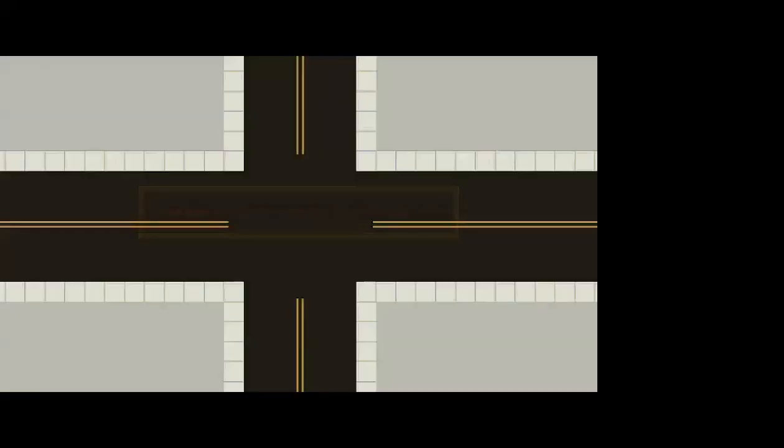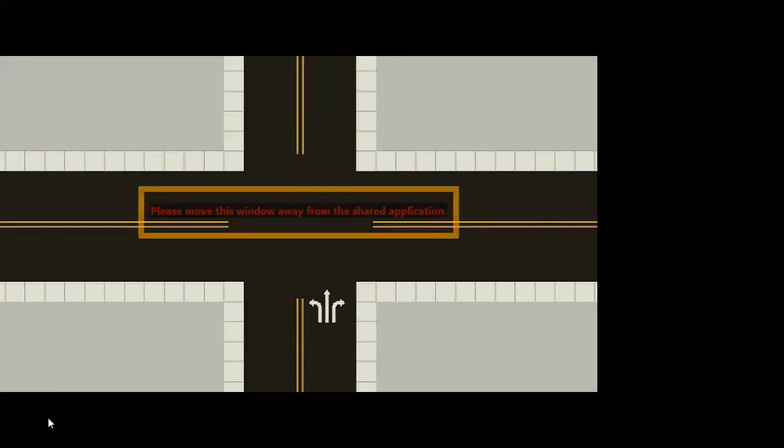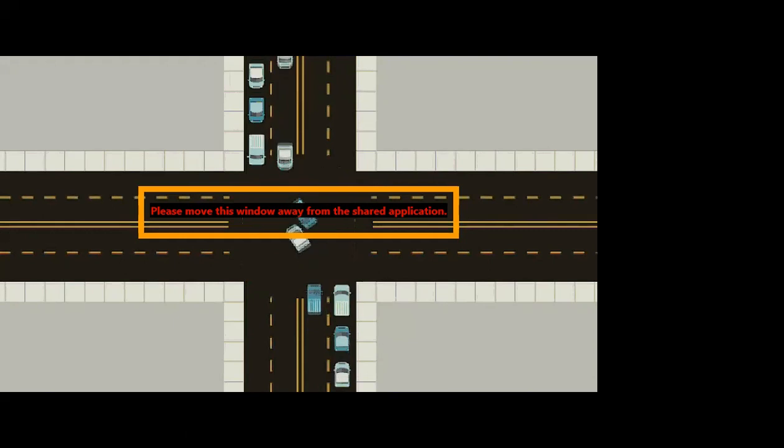At each approach to an intersection, there are 3 directions vehicles can go, called movements: right, through, or left. Right and through are usually grouped together as a single movement, so a typical 4-way intersection has 8 vehicle and 4 pedestrian movements. These movements can be grouped into phases of the traffic signal. For example, the left turn movements on opposite approaches can be grouped into a single phase because they can both go at the same time without conflicts.